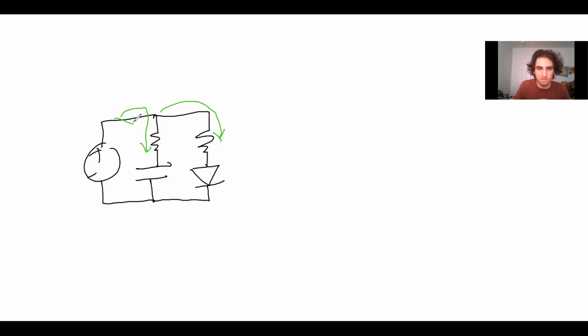So basically this capacitor is going to charge up to VB after some amount of time, right? And then once it charges up, let's say I just disconnect these terminals. Now it's going to discharge and light up our LED for a small amount of time. So the problem that we have is that our capacitor is really small.